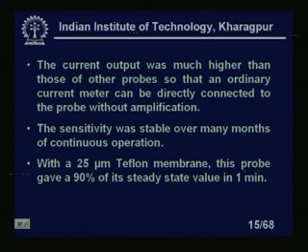Okay. So, it is quite fast, though not as fast as the Clark electrode, but as I told you, fast response time is not a very rigid requirement for bioreactions. So, in that type of application this probe can be nicely used. Most important thing, it can be used over a longer period without any recalibration or recleaning.